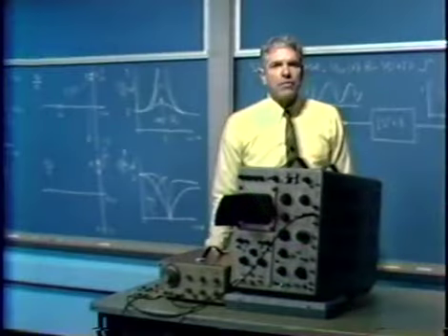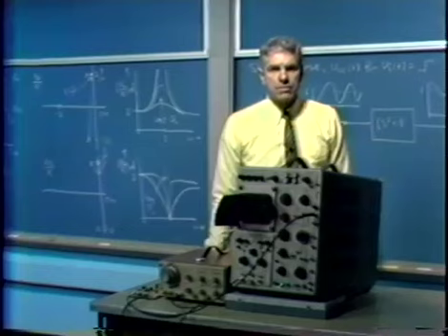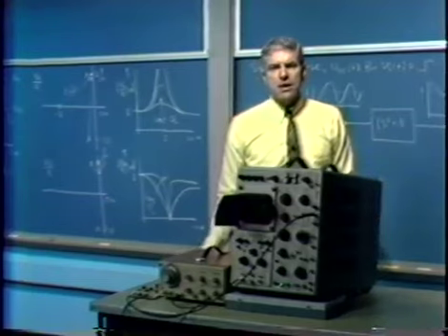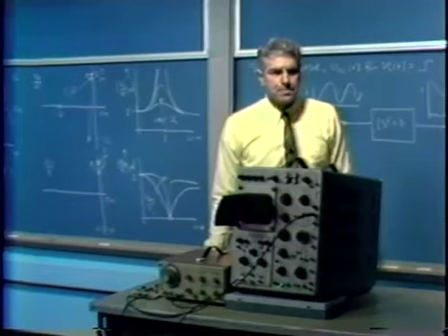Again, bear in mind that this amplifier only has a capability of getting closed-loop pole pair damping ratios of something like 0.1. We don't have a particularly large value for A0 in this experimental setup. However, if we were very careful and had a high gain amplifier and very precisely adjusted the T-network, we'd be able to get very, very sharp nulls out of the rejection amplifier. This offers a good way, for example, to build a filter that eliminates a particular disturbance, possibly 60 cycles from a setup where that's a disturbance.